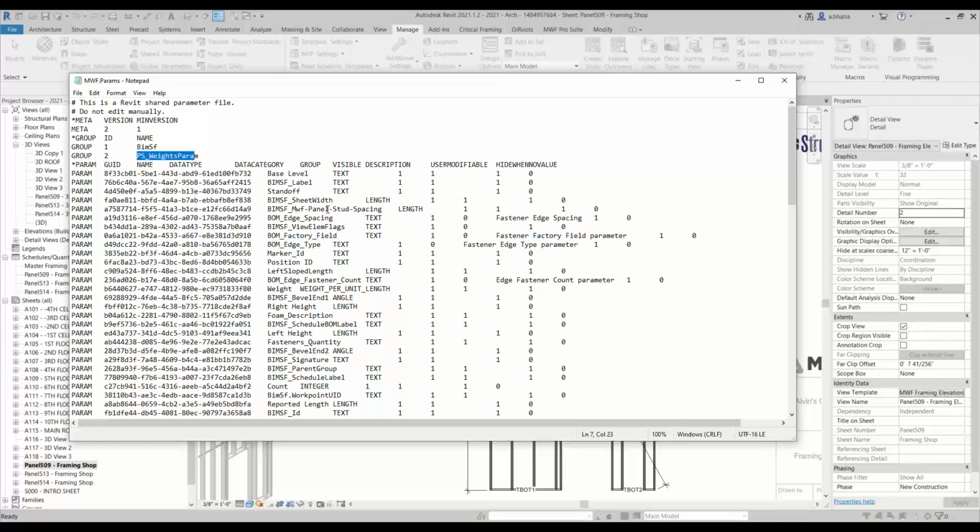Shared parameters are the most commonly used because they can be transferable from project to project. So if I build a family and I use these parameters within that family, and I move that family from, say, project 1 to project 2, the data will remain the same, or it will grab the data from the same location, because what Revit uses is the GUID.